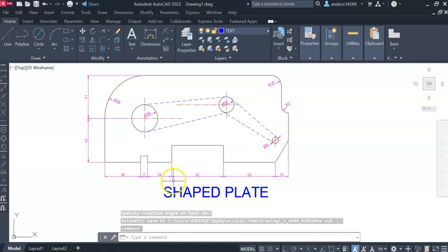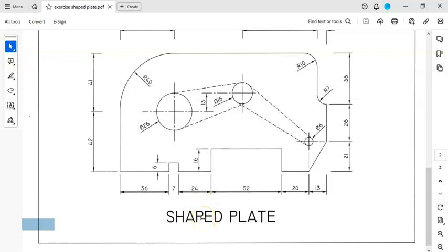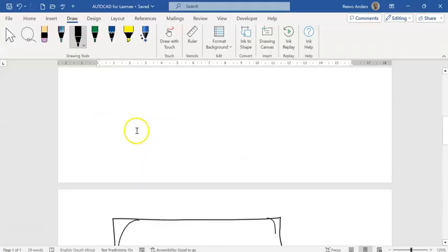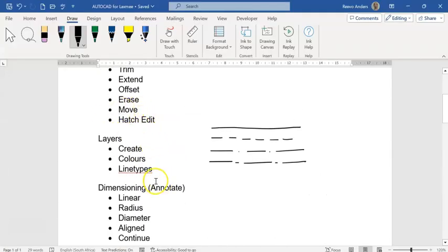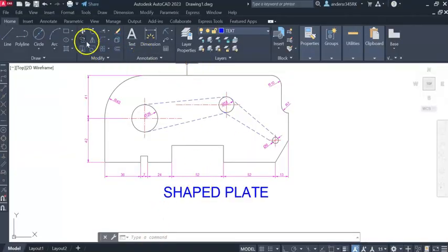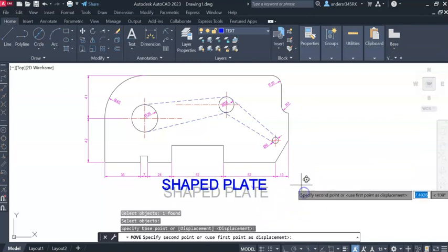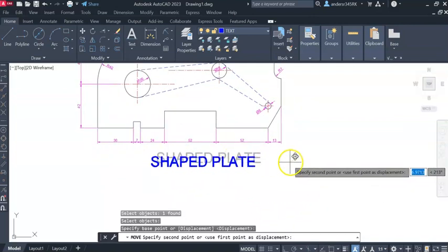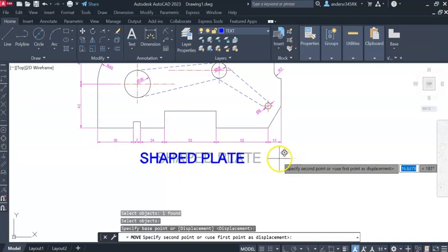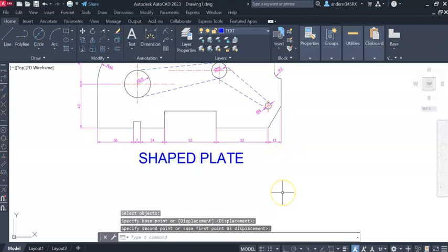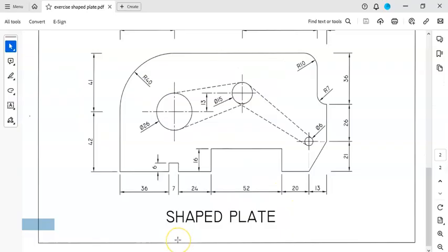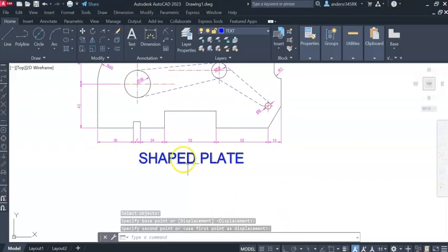Sitting there nicely. Notice it's a bit off center. So what are we going to do? We're going to move it to the right place. I go to move. Move what? Select objects. Click anywhere on it. It says select objects there. There's no more, so hit enter to say there's no more. Grab it anywhere, click there, and I'm going to put it somewhere in the middle, like so. Click it there, and that's where it's sitting, and it's looking so lekker. Okay, right. So that is how you can do that.